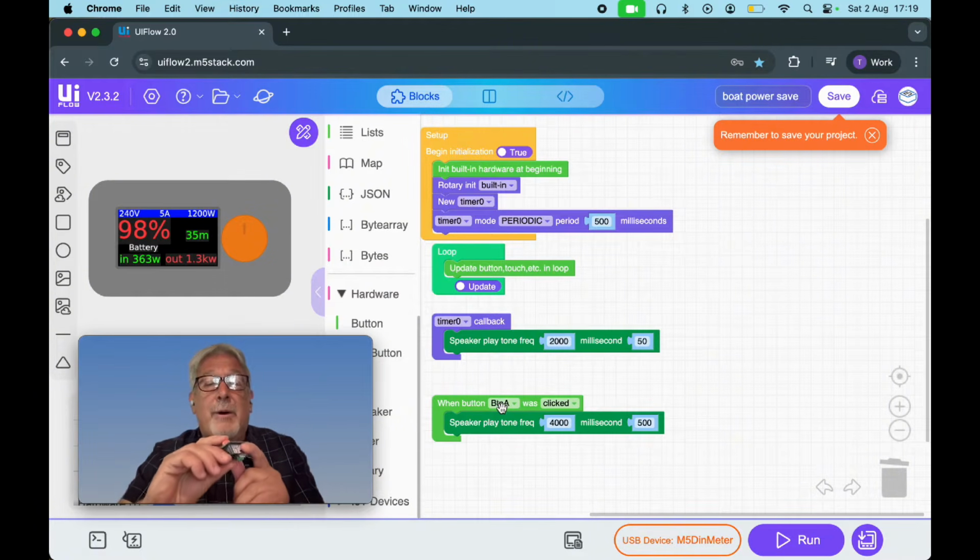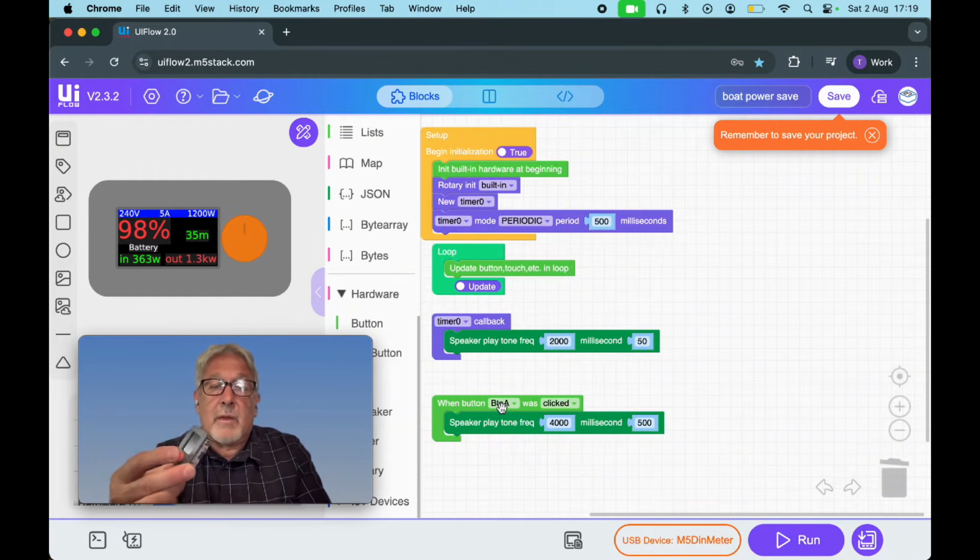So you can't press this like crazy, because that tends to break mains devices if you flick them on and off too quickly. So it's going to have a little bit of hysteresis in there to slow you down. Everything will work without this. If this is not powered up, the relay will be open and everything will just work.